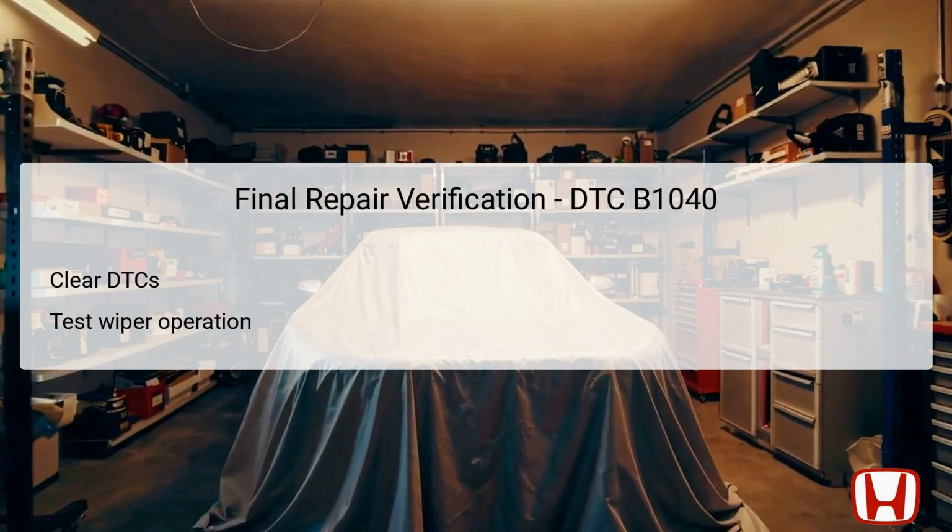After completing the necessary repairs and replacements, the next step is to verify that the issues have been resolved. Begin by clearing the diagnostic trouble codes, DTCs, stored in the body control module BCM using a diagnostic tool. This step helps to reset the system and allow any new operational conditions to be recorded.